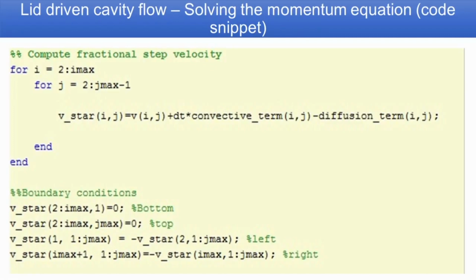Again we should recall what we did for the u velocity on the bottom wall. Because we are following a staggered grid arrangement, we do not have a node coinciding with that wall, so we need a rearrangement in such a way that the boundary condition is actually enforced. For that we have an extra ghost cell or ghost node. The average between the ghost node and the immediate node adjacent to the boundary location, that is the left side wall, is written in this form.